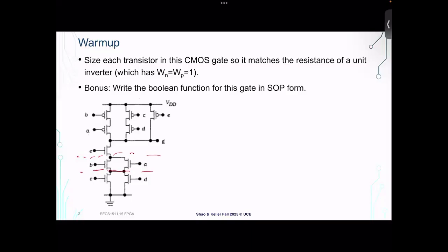When we talk about a strong transistor, that's a wider transistor. It has lower resistance and it can drive more current. Okay, you'll hear this concept of stronger drive or weaker drive is a common simplification to think about this. So we have three in series, and so each of them needs to be 3 times as strong, right? In order to match the drive of the inverter.